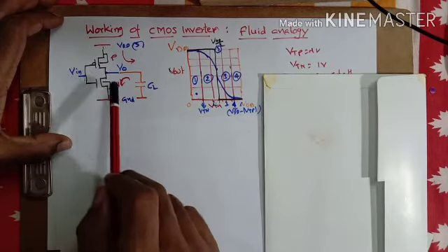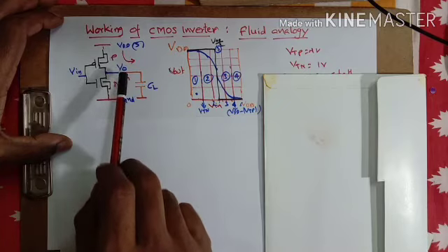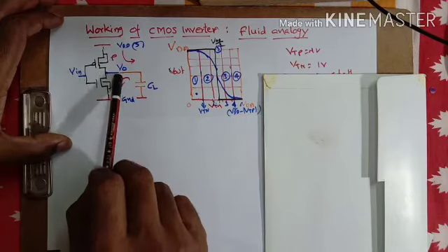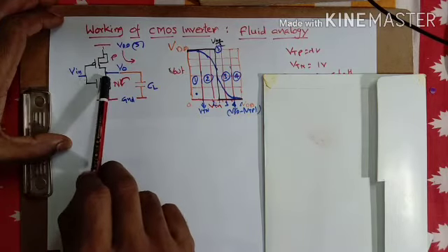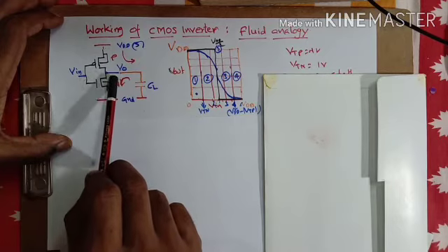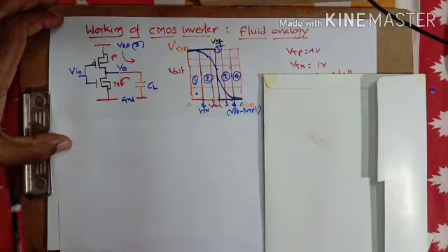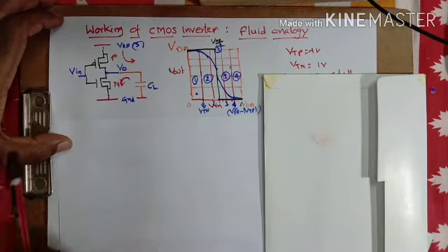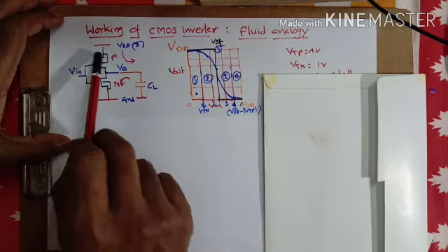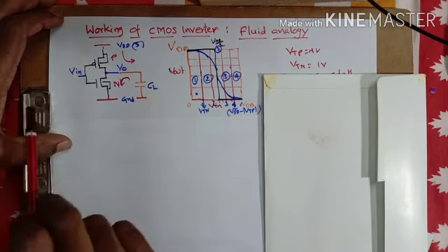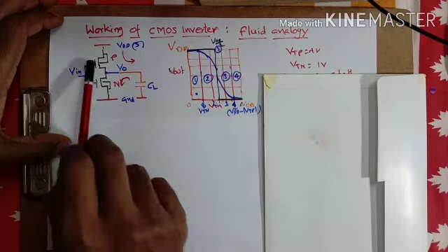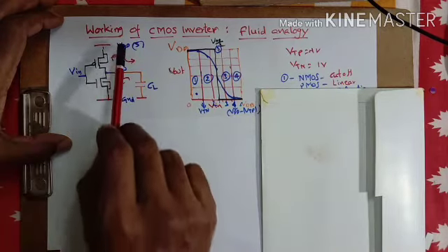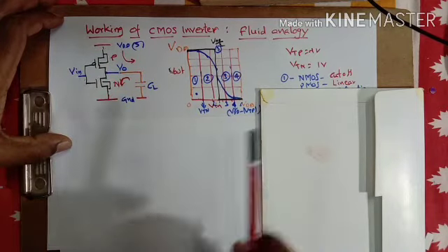And that is also, there are no negative voltages here, but only the relative voltage we have to see here. The relative voltage from drain to source here is again negative because V0 is always less than VDD. This is an intermediate node voltage that is expected to be less than VDD all the time. So that is making VDS for PMOS also negative and VGS for PMOS is also negative there. So that is turning on the PMOS transistor. VGS for Vin equal to 0 for PMOS is minus VDD and VDS is V0 minus VDD for PMOS transistor.